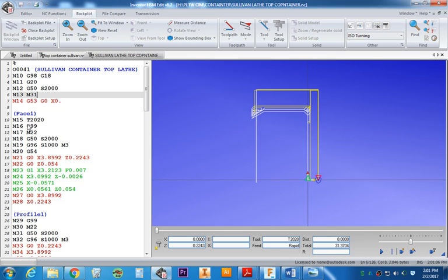Tool 2, we're going to turn on feed per rev. Here is feed per inch, but it should not matter because our first moving operation is rapiding. As we go through, everything looks good until I get here, line number 15 on my code, sequence number 20 right here. On line 15, I have a G54. We can never have G54s in the program. There's 2 of them that we're going to have to find.